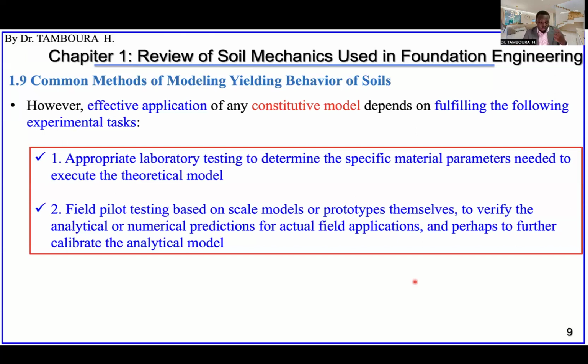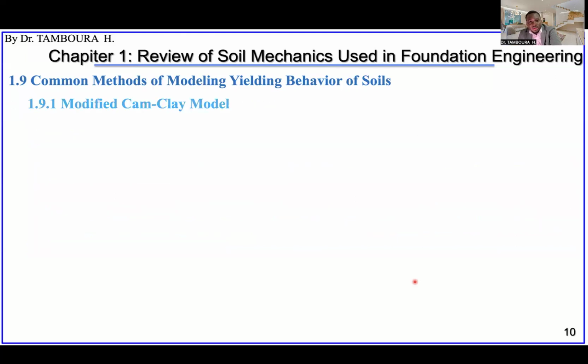And then from that point, you can continue using only that numerical model, because that numerical model has been validated with the field test result. And from then, you can use only the numerical model. It will help you to save time and money, because if you have to test all the pile that have been constructed, built, it's very expensive. Okay, I hope you understand what I mean.